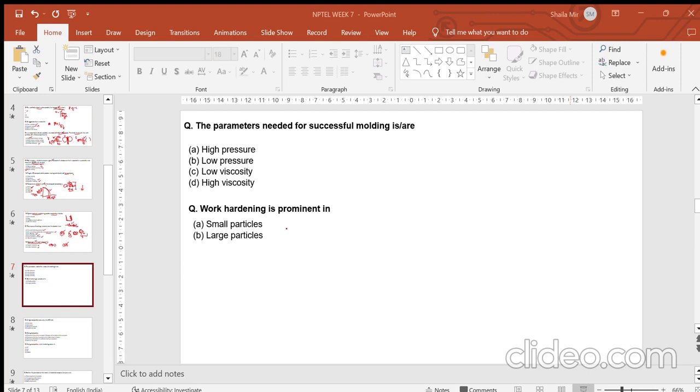So in mixing two metallic powders to form an alloy, there would be a significant difference in the density. But if you are mixing small amounts of lubricants, that is a very small percentage, 0.1 percent, less than 1 percent, 1 to 2 percent. Even if you see it was 8.9 to 8.75, there was a difference in density, but obviously it will not matter because the fraction of the material added is very low, and the density of your lubricants and all of these materials is always low because they are organic molecules.